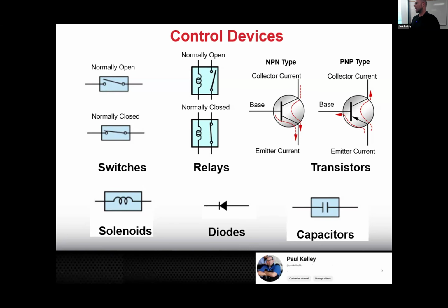Make sense? And that's what's really going to separate the entry level from the professional, is when you don't have to throw two or three parts at it before you figure out the ECM is bad. You'd be able to measure at the ECM and say, oh, this ECM's not putting out voltage. I suspect the transistor. Let me make sure I command it on with the scan tool. It still doesn't put out voltage. Uh-oh. Makes sense?